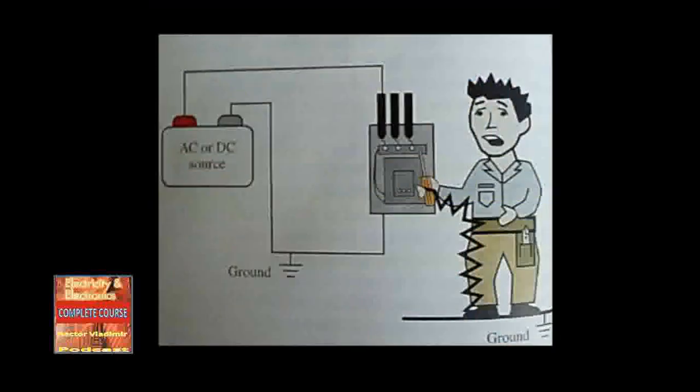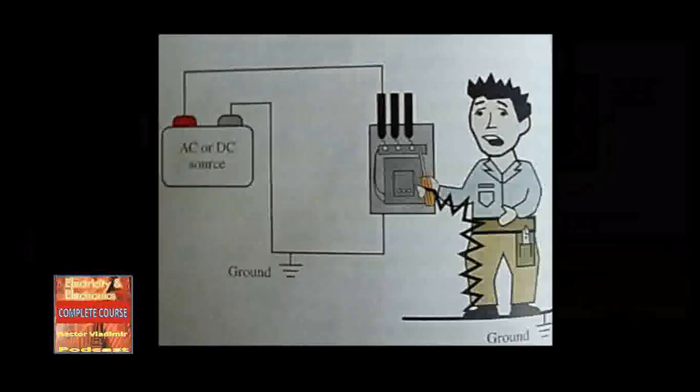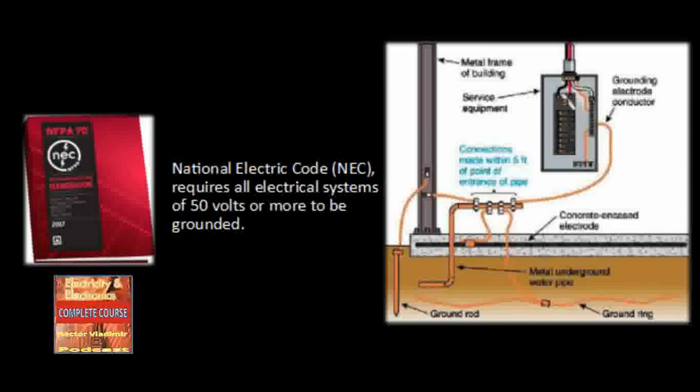Some electrical systems do not connect directly to the earth. Instead, the metal enclosures or metal conduits serve as a ground or as a return path for current. If a person touches an energized conductor, that person can easily serve as the path to ground, as shown in Figure 2-21, and experience electric shock. Also, if a system experiences an electrical fault, the metal enclosure or conduit may have a higher voltage potential than the earth ground. Thus, a person touching the enclosure or conductor can experience electric shock.